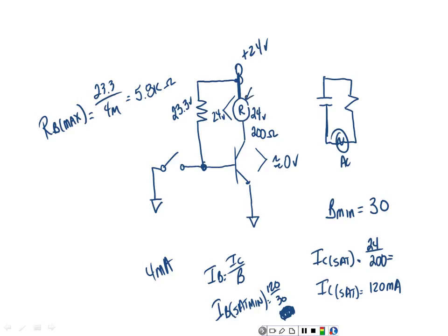And when it does, the 24 volts don't mean anything, because what determines how much voltage it induces back into that coil is the number of loops of wire, the strength of the field, and the speed of the motion. So we could get 100 volts off that coil if we didn't do something with it. 100 volts, a 3904 would probably break over, and as soon as we broke it over, collector to emitter, what would happen?